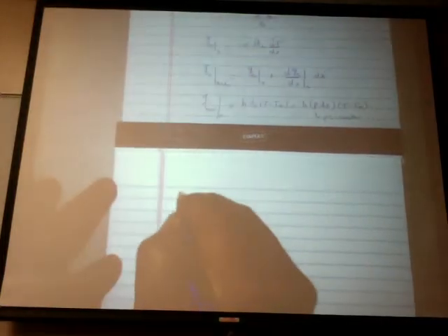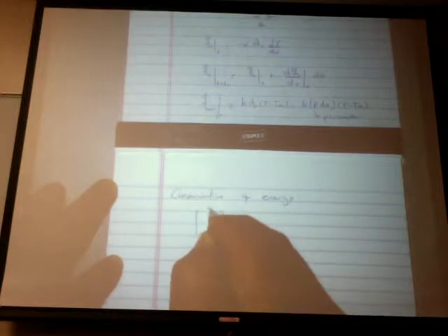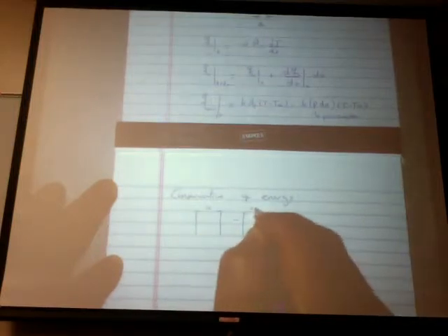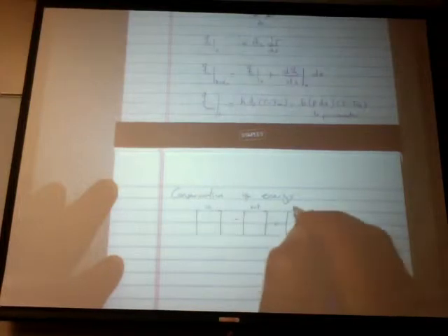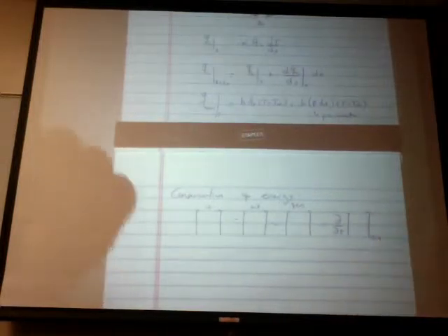So this is how we formulate the equation, and then conservation of energy basically says whatever goes in minus whatever goes out plus whatever is generated is equal to the partial with respect to time of whatever is inside the control volume. Let's assume that there's no heat generation, and let's assume that this is steady state. We're interested in the steady state response of this problem.